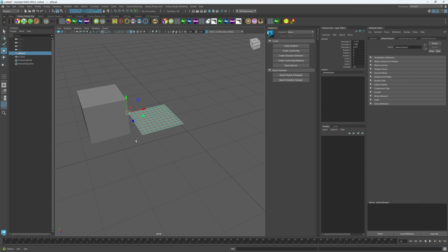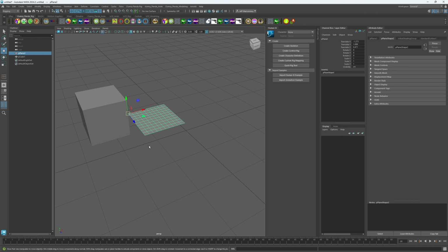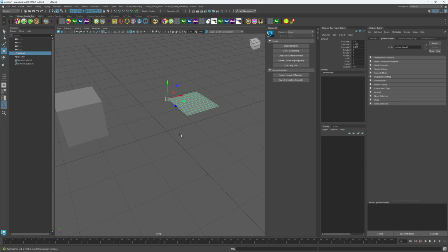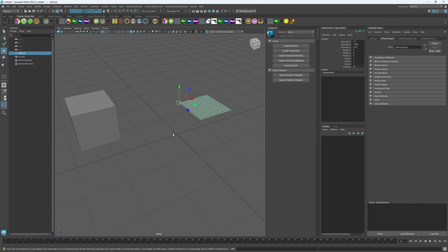Now, snap to grid, which is the X. A lot of times you need to reset your coordinate. So right now, if I activate X or I activate Z, let's activate X, you'll notice that it will only snap in the X axis. If I activate Z, it will only snap to the Z axis no matter what I do.